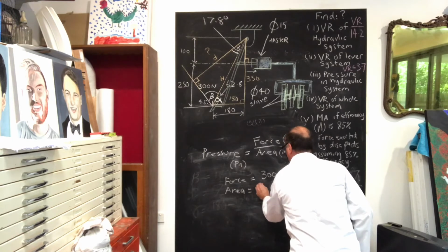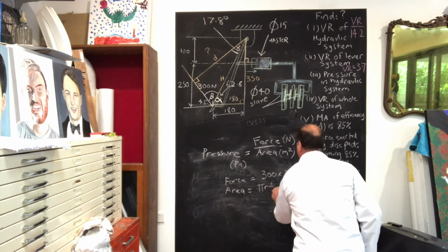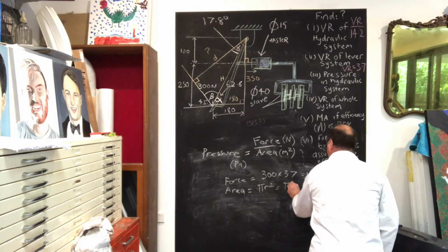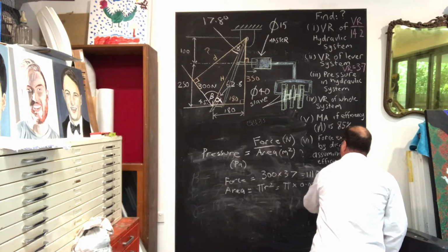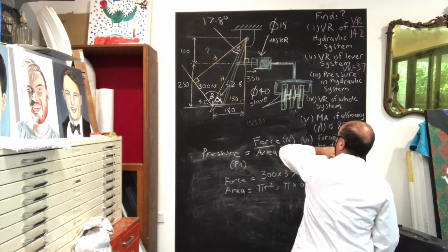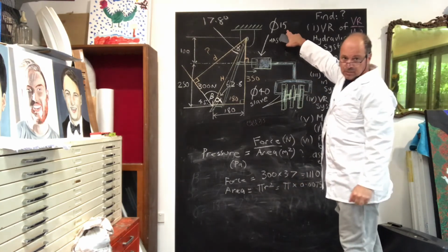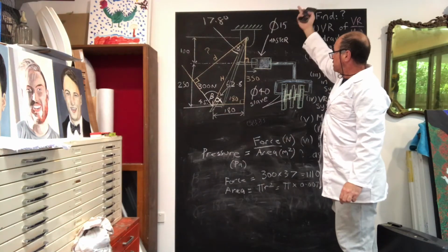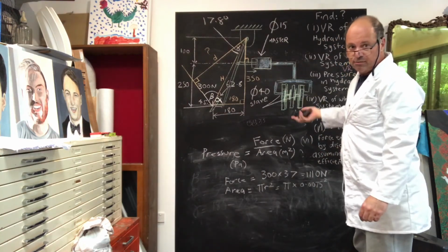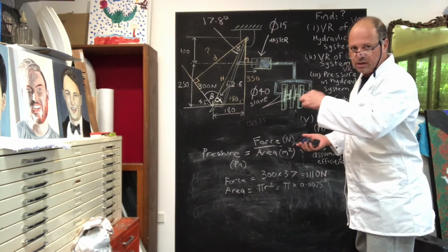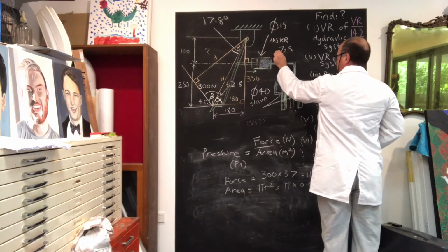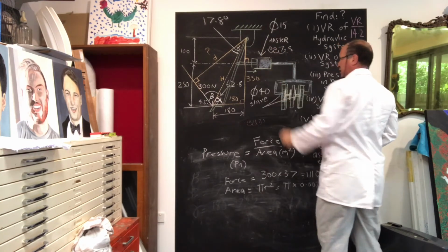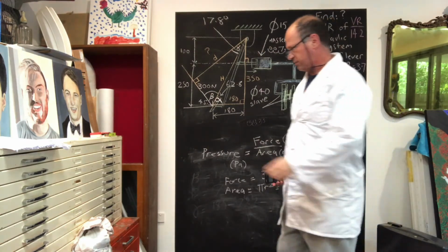area of a circle, pi r squared, which is equal to pi times 0.0075 squared, because I've taken 15 millimetres, because whenever you see this without units, it's going to be in millimetres. 15 millimetres, I've halved it to make it 7.5 to get a radius, and then I've converted it into metres by dividing by 1,000, and all I've done is taken my 7.5, and I've gone 1, 2, 3 to move my decimal point 3 places. That's basic primary school stuff.